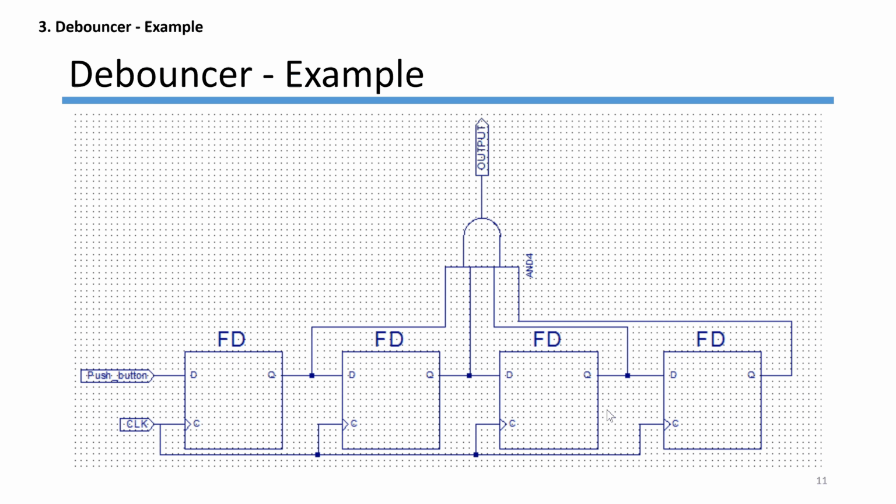Now, this is the example debouncer in your template project file. As you can see, the input is fed through multiple flip-flops, and it's only when all 4 of them push back the same result that the clean signal is then outputted into your digital circuitry.